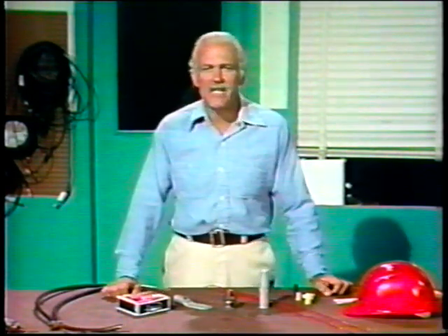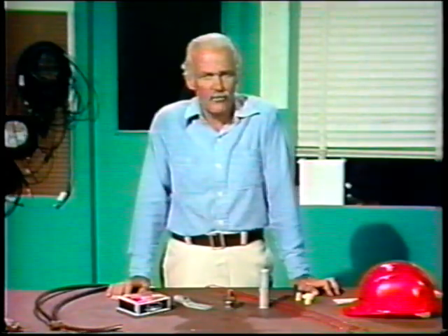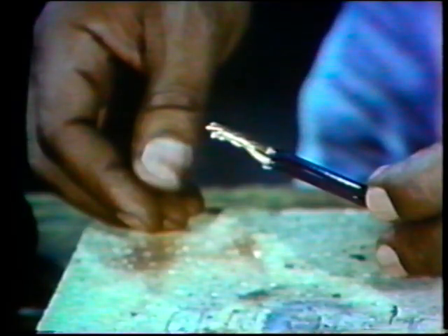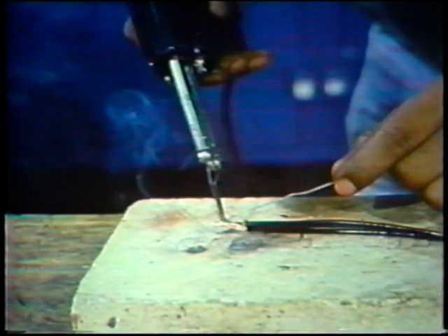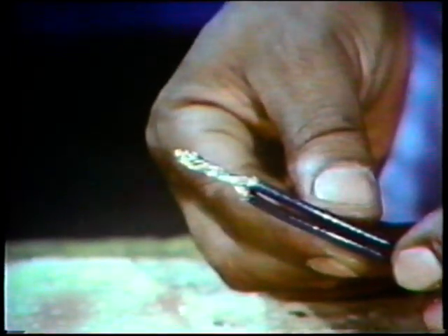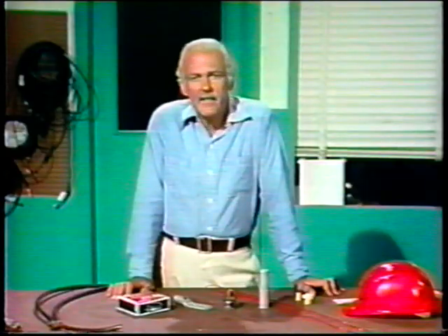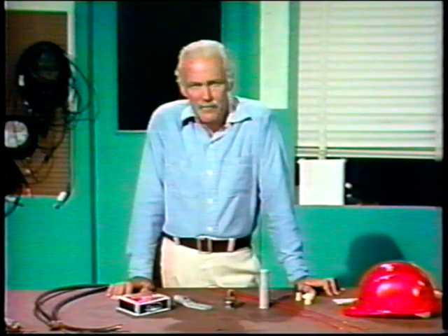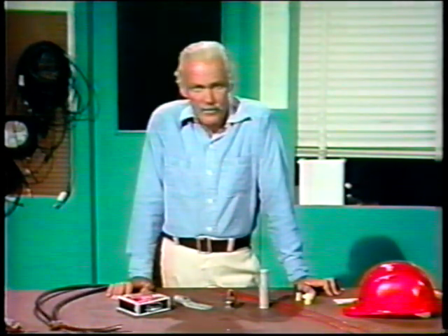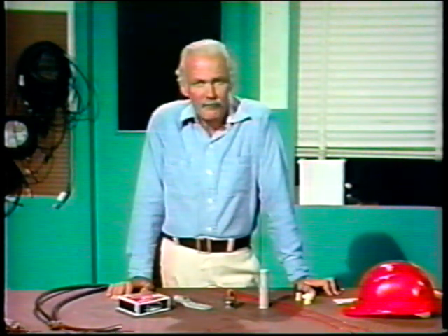Thermal connectors use heat to make the connection between two conductors. One common method of making a thermal splice is to twist the ends of the conductors together and solder them. Now, this particular method requires no additional connecting device, but it will require insulation. Insulating splices is usually the final step in a splicing procedure, and it's usually done with electrical tape.